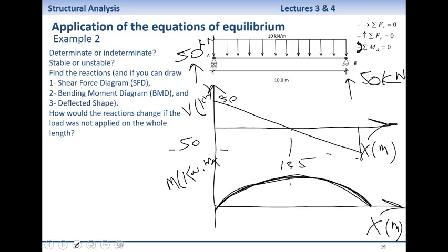But please use the equilibrium, write the equations, cut the beam, and construct the two diagrams yourself. You've got the final answer. Calculate the reactions and then cut the beam once and come up with the equations for V and M. Any questions?